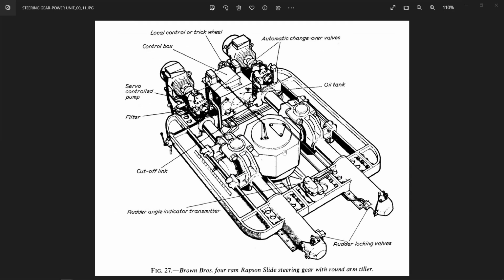So here you see the solid rudder stock in the center, which is keyed to the tiller arm. The tiller arm is connected to this solid tiller, which is one piece, this entire piece, and you have got a solid tiller arm. The central piece is solid, and now you see these are the forked ends, basically the forked ends of the ram. Now this arrangement is an older arrangement.